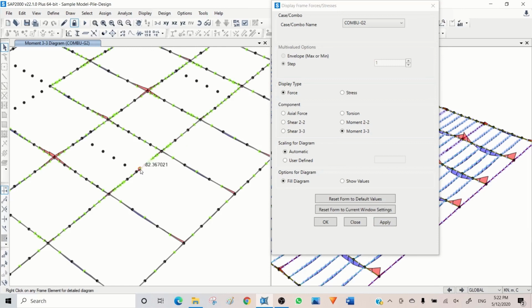So really back to the compatibility of deformation and how the loads will be transferred. For this slab, is that realistic to use such a low stiffness? My answer is no. The reality is the slab can take the load, and the slab is able to transfer load to the corner. Yes, beams are working, but when the span is such a large span, we cannot expect that the slab deflect that much. So my suggestion is keep the beam 0.7, but keep the slab 0.35 as it was at the beginning.